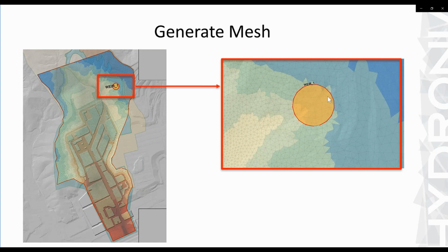And you can see here that we are included in the mesh, the inside of the tank. So this will allow us to not impose any discharge. We let the model calculate the outflow from the tank and not impose a value here. We could have used the source component to do that and impose a hydrograph that would represent how the volume of oil will be released. But for this example, I chose to use the model to calculate directly that flow.